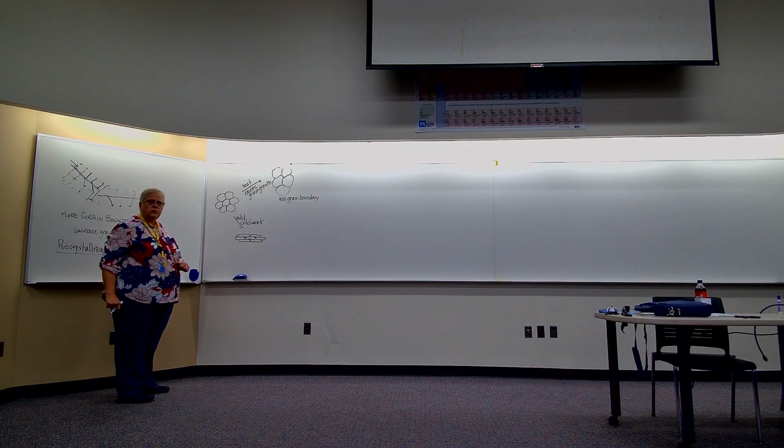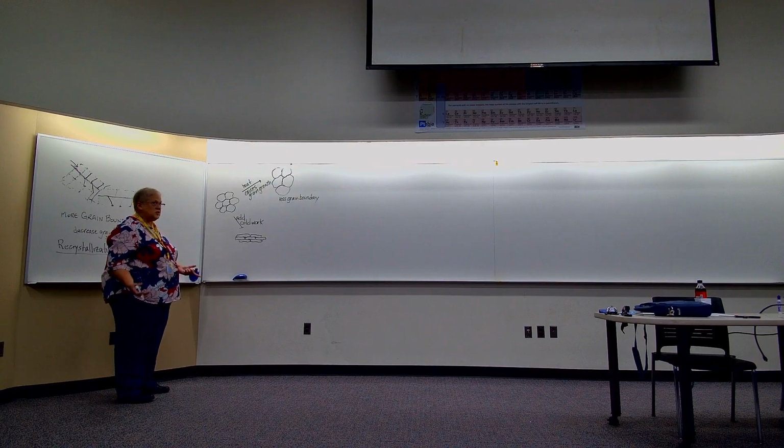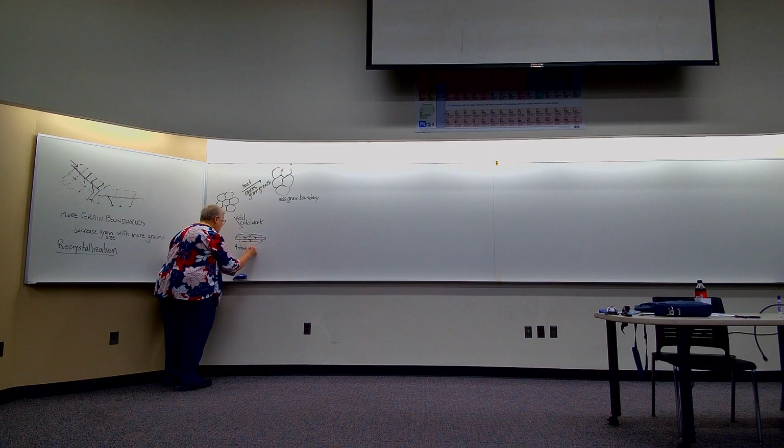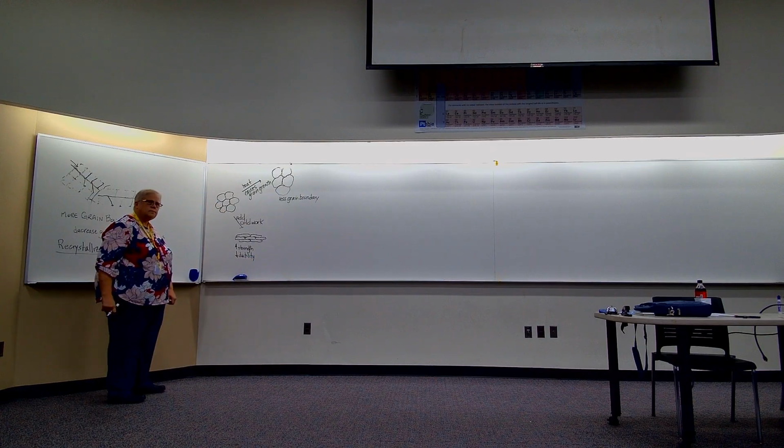What happens to the strength when I cold work? It increases. What happens to the ductility? It decreases. We just did that. So if we just take this and we add cold work, we get increased strength because of all those dislocations and decreased ductility. That was our cold work process.